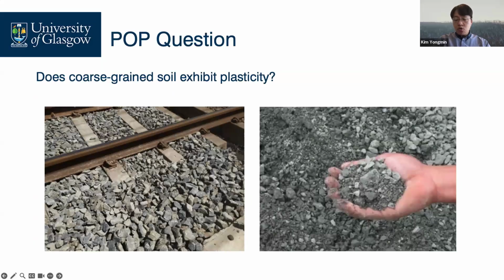What about the coarse-grained soils, do they show plasticity? Yes or no? You can take a look. These are cobbles and gravels and a bit of sandy soils. It looks like coarse-grained soils are non-plastic. Yes, no plasticity behavior.